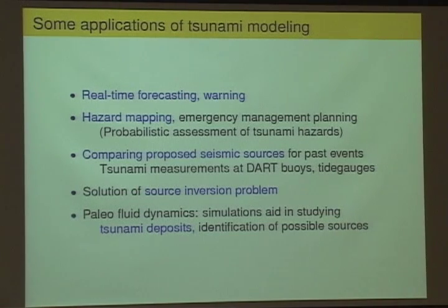So there's a number of applications of tsunami modeling. I've already talked about a few of these, but other potential uses of tsunami modeling in particular is to look at comparing different proposed seismic sources for how the earthquake actually moved, and look at the resulting tsunami that would be generated from a hypothetical earthquake and try to match that with the data that's actually recorded.